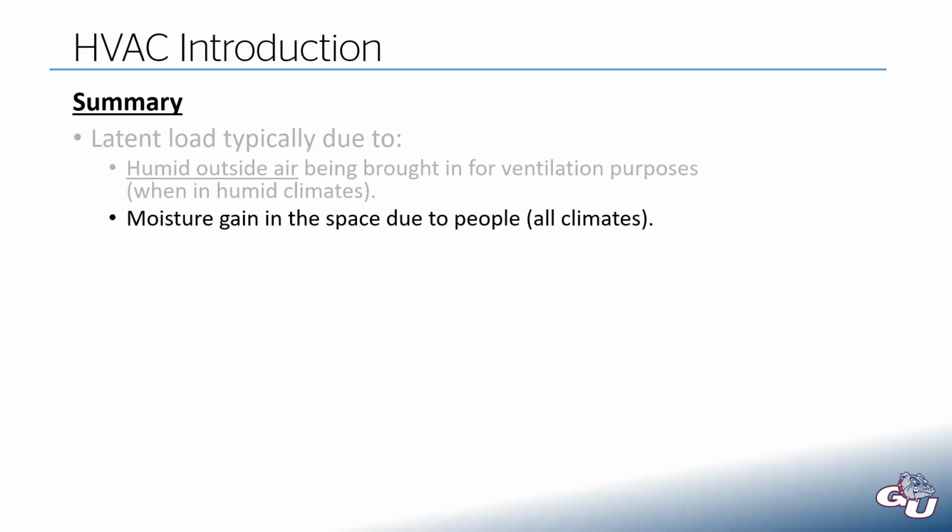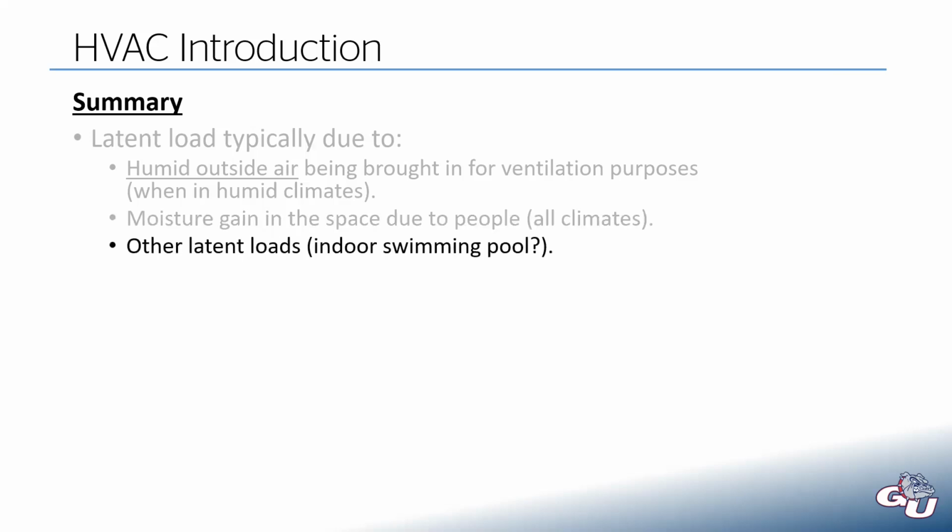And that's going to be true of all climates, not just humid ones. You could have some other latent loads as well, like an indoor swimming pool. At least every indoor swimming pool room I've ever been in is really humid. And so if you're pulling that air back into a cooling coil, there's going to be a lot of latent load there.